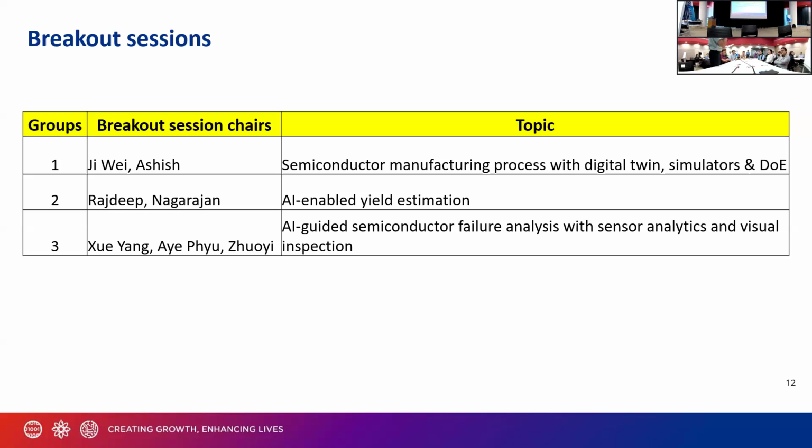And the last one is that foundries generally look at one process shift as one particular target they need to achieve, but there could be multiple processes shifting collectively, and the correlation of these shifts can also impact the yield quite a lot. So the models that we build for yield prediction have to account for correlation between multiple process parameters, which might not be looked at by each process person per se. So we need to account for these correlations as well. So that is the summary of current challenges in this particular video.